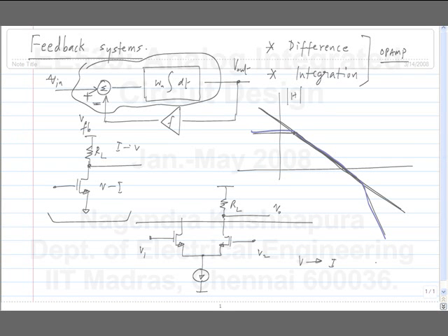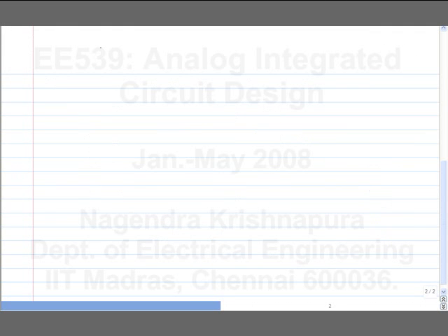So, we can represent this as an amplifier, but a more precise representation is that of a transconductor followed by a load resistor. So, the amplifiers we have are of this type. This is the symbol for a transconductor, and if we use a differential pair, we can take the difference between two voltages.